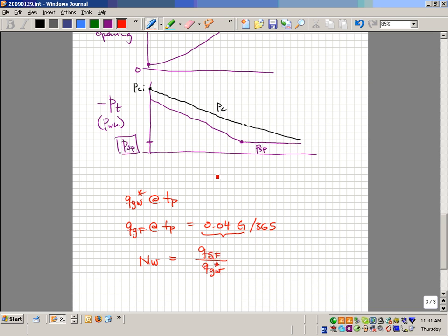That's only a function of basically the recovery factor at the end of plateau. You change the recovery factor at the end of plateau, you've changed the average pressure. It's also, of course, a function of PT minimum. Okay.